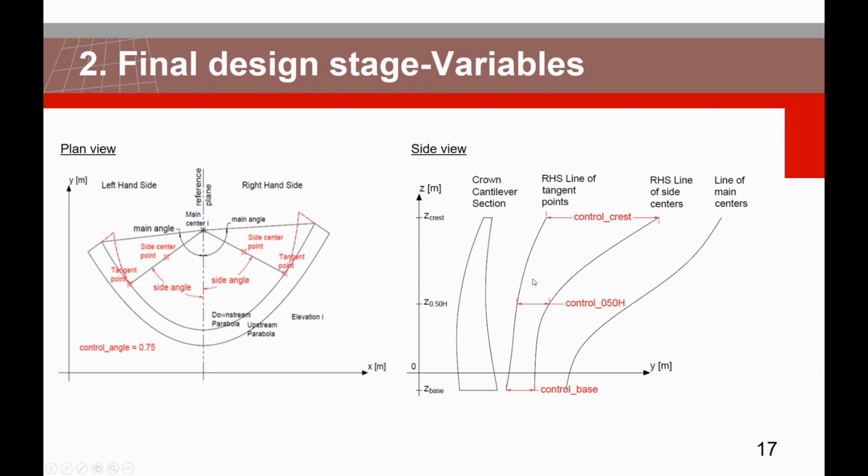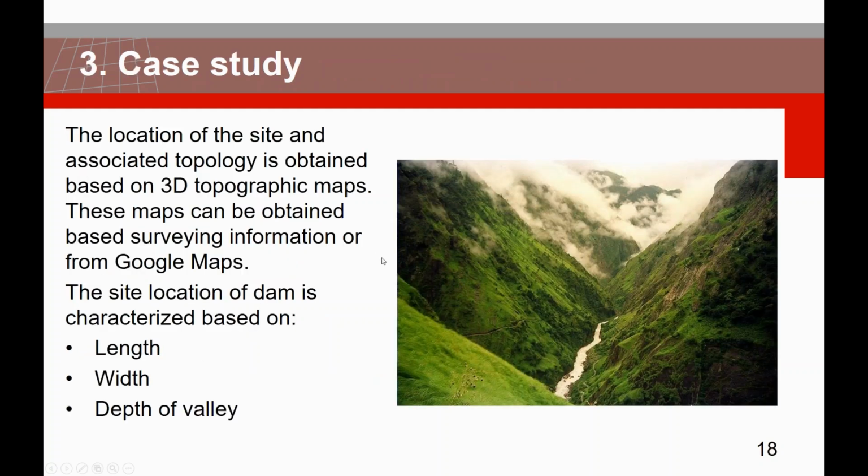By knowing these lines, we can add concrete around the foundation area along the dam height while keeping the smoothness of the downstream face, which is very important, because if at this stage we introduce any dimples, then we are going to create stress concentration areas that we don't want to have there. And this was the end of the process.